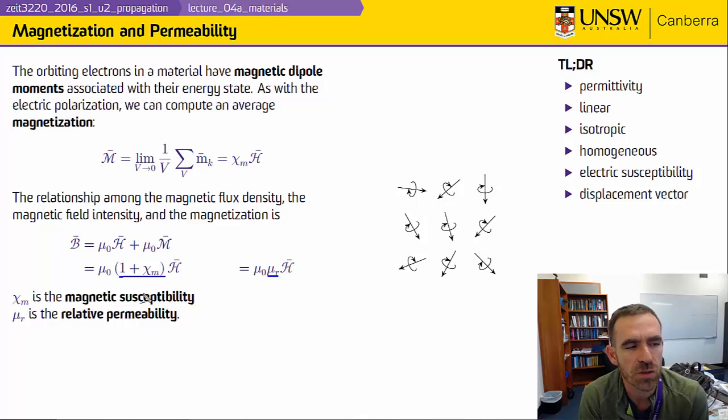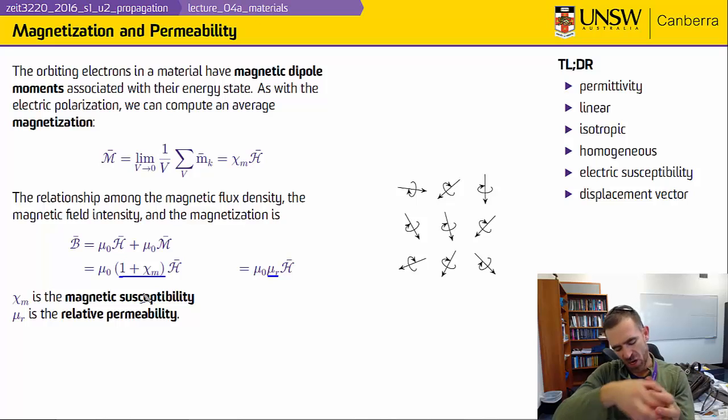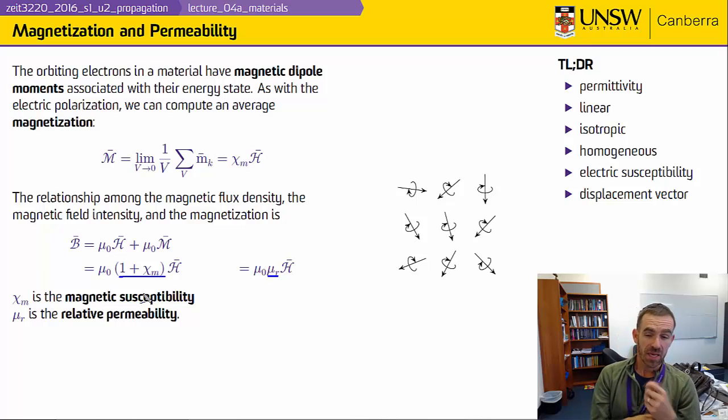You can read through your textbook and you will see that for most materials their relative permeability is like 0.99995 something. But a class of materials which are ferrous materials, iron being the most common, but there are ferrites and other types of metals that have this property, you can actually have very large permeabilities, mu sub r's of several thousand. And what this means is it gives you a very strong concentration of the flux. And so, for example, if you're making a transformer, you will wind a coil of current around an iron core. And that iron core very much concentrates the magnetic fields, gives rise to a very large magnetic flux density. And in effect, you can turn off the current, and that magnetization remains in the material, and that has to do with the physics of how that material is put together.